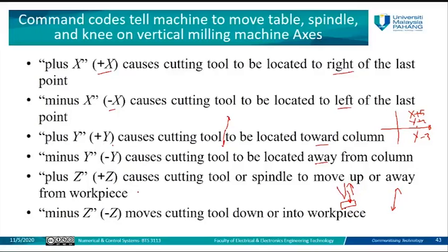That means in the coding, after you select the mode of operation, which is G91, which is incremental, you then define the coordinates for the machine to move. So you will say, for example, x +5, that means go right by 5, then y -2, for example, it will go in the y axis away from the machine by 2, and so on.